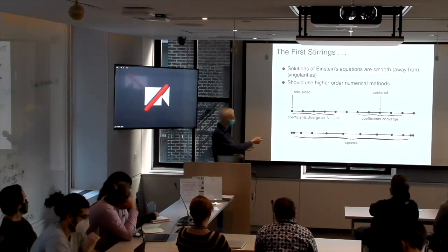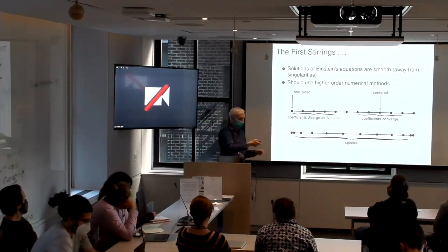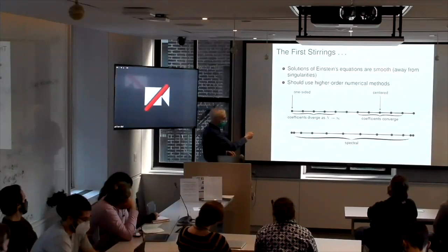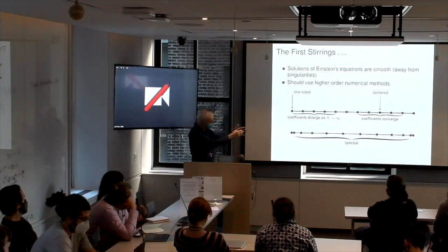So the way we handle this in practice, if this is an interior boundary, you divide your grid up into subdomains. We have another subdomain on this side, and we communicate the information that we need at these missing grid points, these ghost zones. We communicate that information to this processor so we can use a more centered differencing formula here, and we maintain the stability that allows us to use higher order methods.